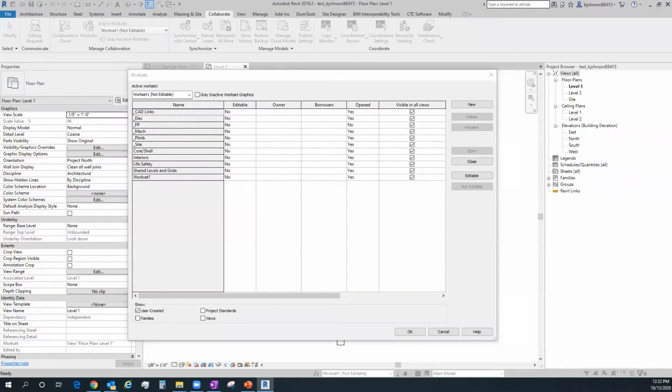Keith also says, can you go into more detail on what to do for model maintenance? As far as other things that I would do for model maintenance, usually I would open up the file detached. I would usually do that at a time when nobody else is in the file. Notify the team first and say, by the way, we're doing model maintenance, say every Monday morning. That's when we get all of our updates from all of our subs, right? So as we do the new adds or the downloads of those files, place them on the server where they go, or write the old locations, maybe make archives of the previous version so we have copies in case we need them. On our model itself, that might be a good time to do model maintenance.